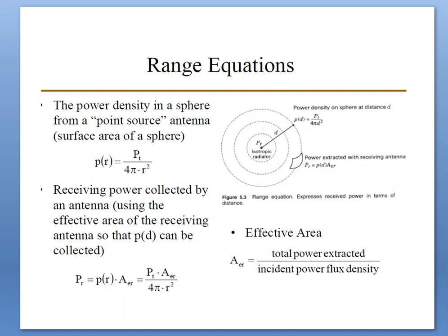The link budget monitors the ups and downs of the transmitted signal from its inception at the transmitter until it is ultimately received by the receiver. The computation tells how much signal-to-noise ratio is received and how much safety margin exists beyond what is required. The process starts with the range equation, which relates power received to the distance between transmitter and receiver, and we develop a range equation.